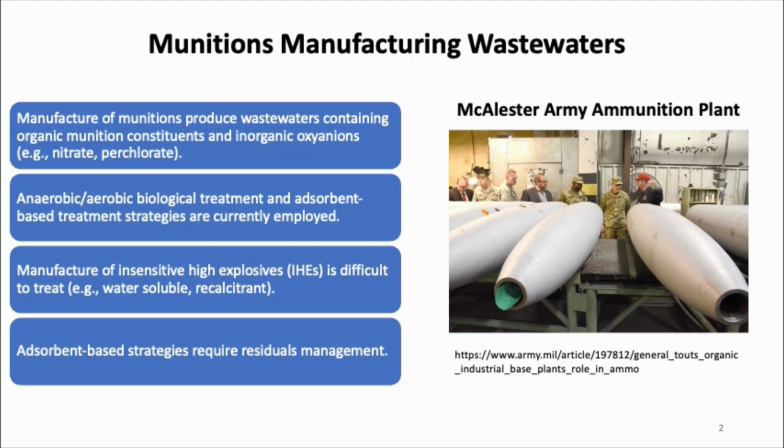The manufacture of the insensitive high explosives has made treatment more difficult because these compounds are more water soluble, so they're less amenable to absorptive treatment, and they've also shown to be very recalcitrant in some cases. So the traditional aerobic, anaerobic biological treatment processes do not work very effectively on them. Additionally, with these absorbent-based strategies, there is going to be a residual contamination that needs to be dealt with, so there is some concern over how to manage these residuals.